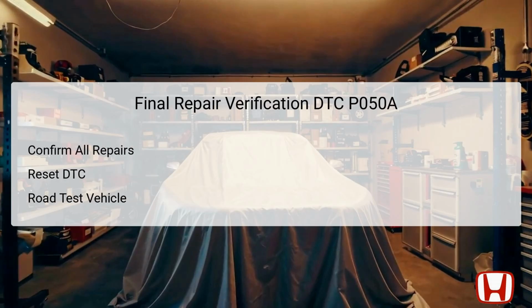P050A. After carrying out all necessary repairs associated with DTC P050A, thorough verification is essential to ensure that all issues have been resolved effectively. Begin by confirming that all repairs have been done according to specifications and standards. Once confirmed, proceed to reset the DTC using the Honda Diagnostic System, ensuring that the system starts fresh without prior fault codes. It is crucial then to perform a comprehensive road test of the vehicle under varying conditions, particularly focusing on cold starts and warm-up performance.